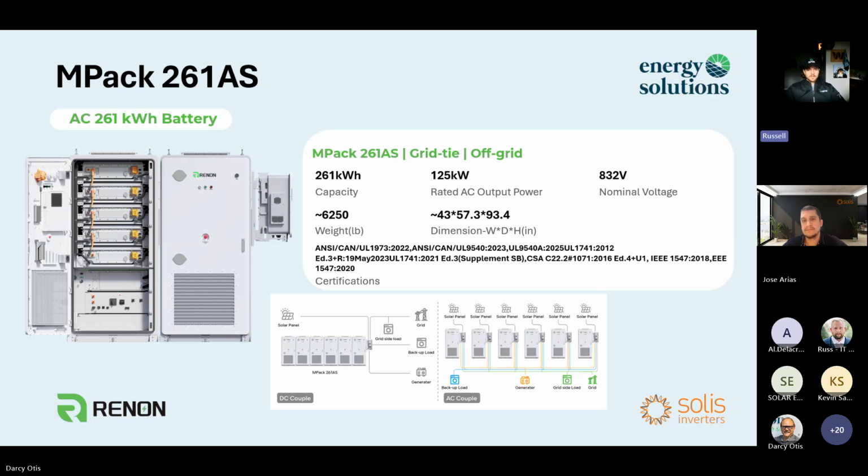Whereas some people are looking much more for resiliency; their total threshold for power consumption isn't as high. Maybe it's only 100 kilowatts, but they want to be able to last without support from the grid for days at a time. If it's a cloudy week, they want to still make sure the lights stay on without having to fire up their diesel generators. And what that means is that you can run multiple of these DC block batteries with a single inverter. So those are the two use case mechanisms that you see across the bottom here.